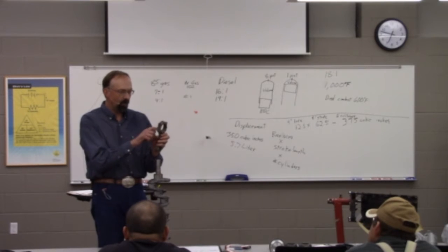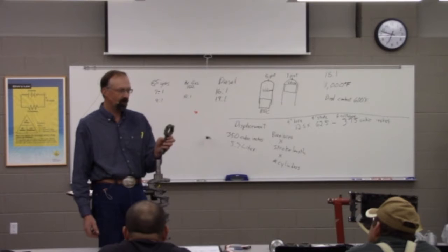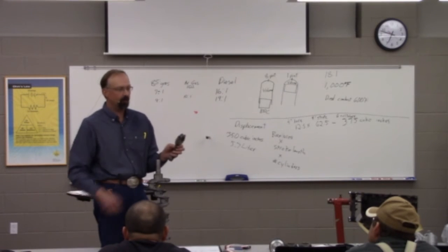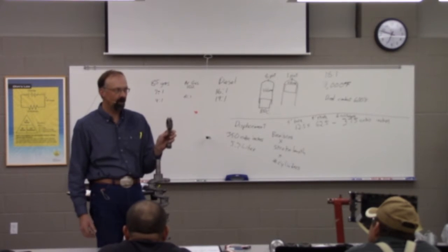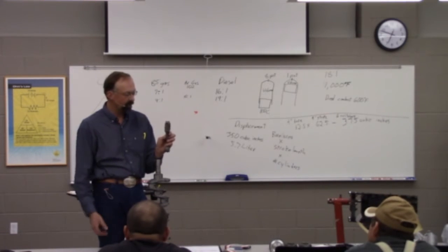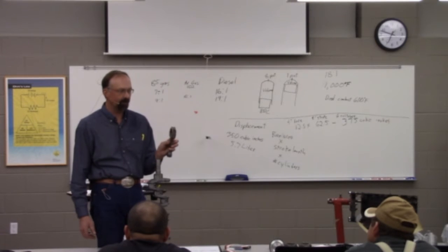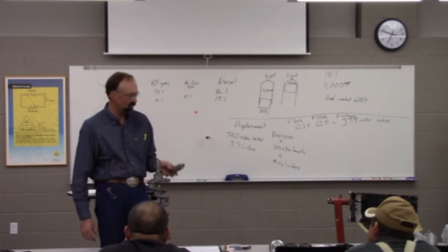But when that bearing gets worn out, where instead of 0.02 of an inch of clearance between this and this, we've got 0.07 of an inch, it's going to flow a lot more oil, isn't it? And when you get to that point, in many cases, your oil pump has trouble keeping up. It can't push enough oil to keep up with all of it we're losing out the sides. So you wind up having low oil pressure. There are other things that can cause it, but that's the main thing that tends to cause low oil pressure: if the clearances that started out nice and tight have been worn to the point that they're real loose.